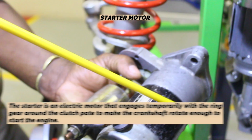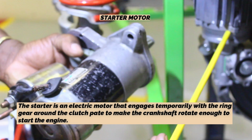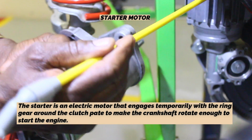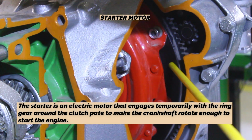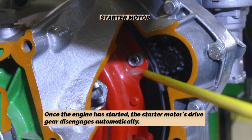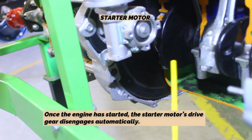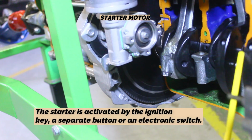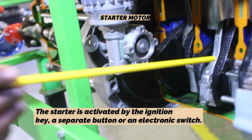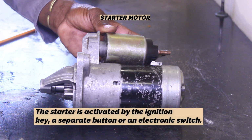Starter motor. The starter is an electric motor that engages temporarily with the ring gear around the clutch plate to make the crankshaft rotate enough to start the engine. Once the engine has started, the starter motor's drive gear disengages automatically. The starter is activated by the ignition key, a separate button or an electronic switch.